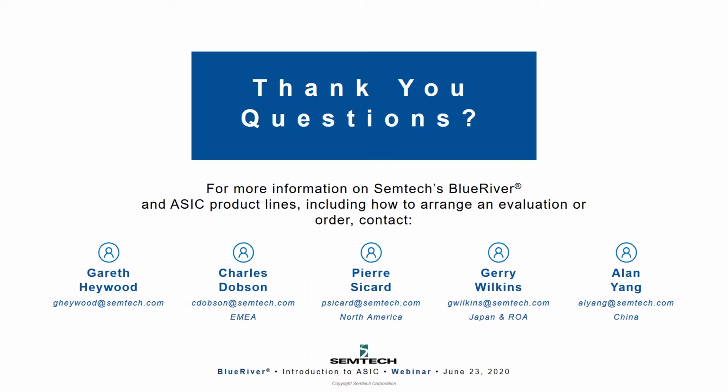All right, thank you. Next question from Stephen Barlow. What prevents the AVP 1000 from supporting 10 gigabit optical ports? It's simply the device configuration. It boots up and can only support copper connectivity. So it needs to see certain handshaking from a 10 gig copper PHY to work appropriately, and nothing will happen if you connect up an optical based solution.